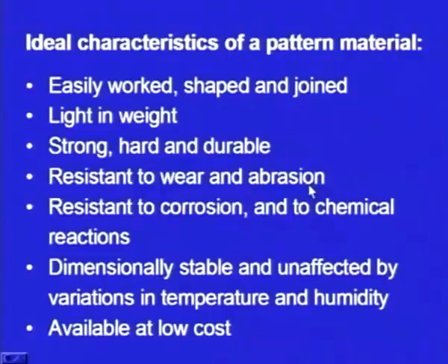When we place the pattern inside a molding box, we start ramming the molding sand, and we compact the molding sand with rammers. It is at that time the pattern is subjected to wear and abrasion. And if the pattern material does not have resistance against wear and abrasion, within no time it will lose its geometry.